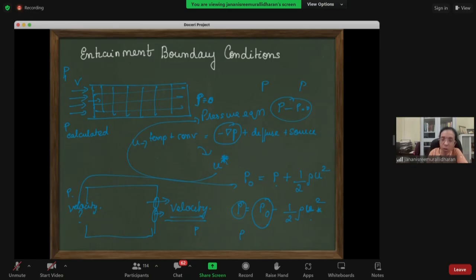So what is the boundary condition that's typically given at the inlet? Here at the inlet, you will be giving something called total pressure, which is equivalent to this stagnation pressure value. So total pressure is used. And for velocity, you will give pressure inlet outlet velocity, meaning the velocity gets corrected with your pressure value once the pressure value is known. That's what you're trying to tell it. So this is for only a flow condition.